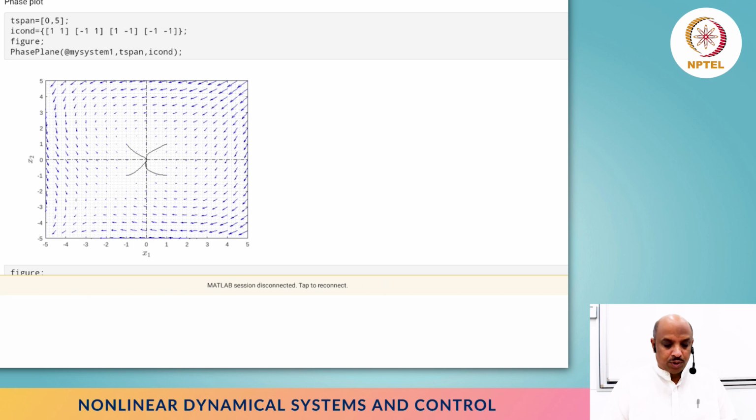That is in general a problem anyway even in the Lyapunov direct method, the second method, where we have a Lyapunov function, the V dot may be satisfied only locally, right? But we have a hope for seeing something globally there, whereas in the linearization method we don't have that hope. So that is essentially the linearization method using linear systems understanding.